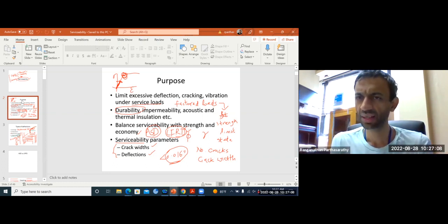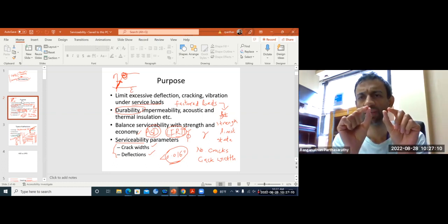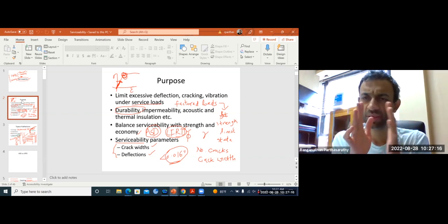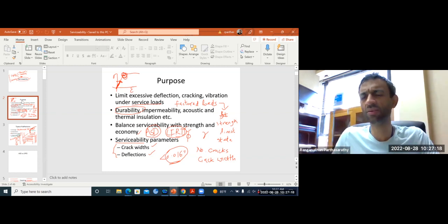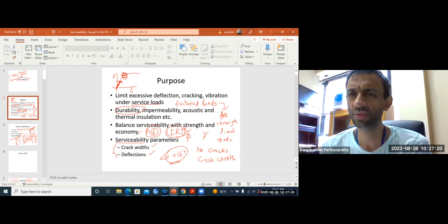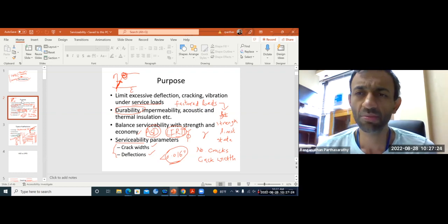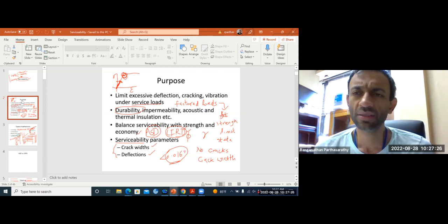We don't want that. If instead you use many rebars of a smaller cross-sectional area, then you will have smaller hairline cracks, but many of them along the length of the beam. That's what you want. Okay, directly we went to beams because deflections are far more important for beams than for columns, which are usually under compression.